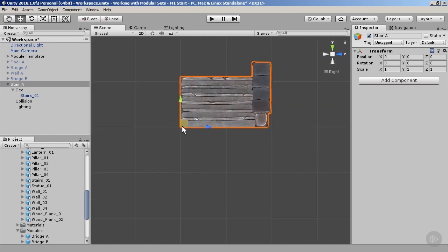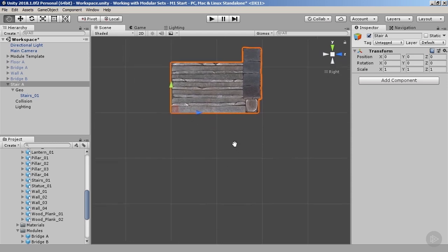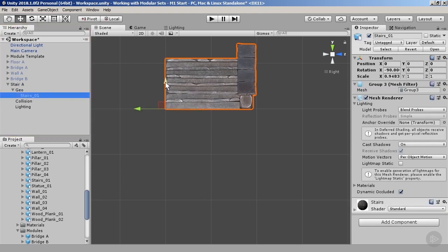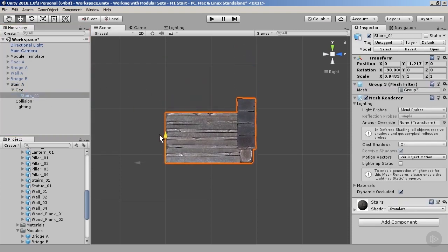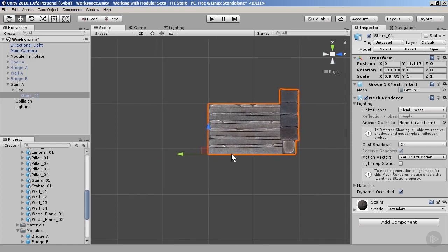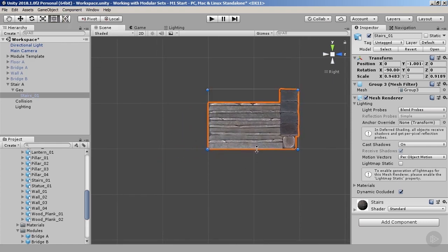Okay, at the bottom here is not really useful. Also, the height of the stair is a little bit more than 1 unit, so that's not really ideal. So let's go ahead and, again, select the stair object here. Just move it down so the top surface is right there at that grid line, and then again, we'll use the rect tool just to bring the bottom edge up.